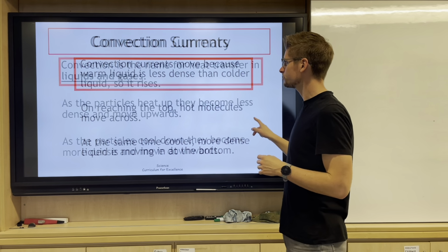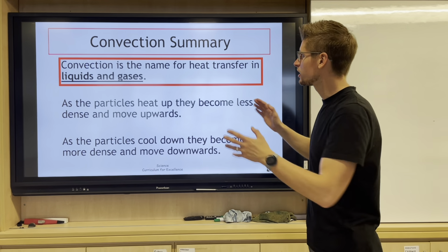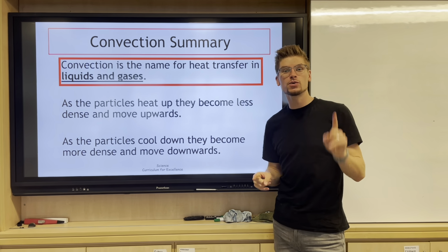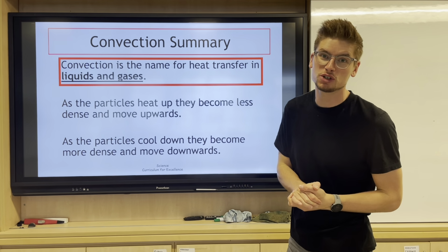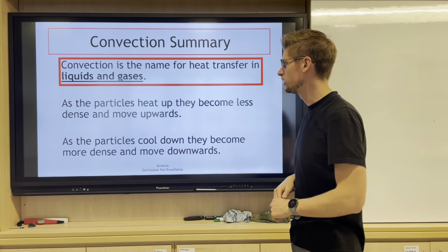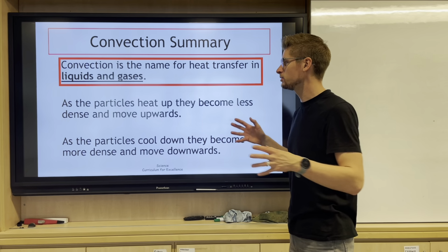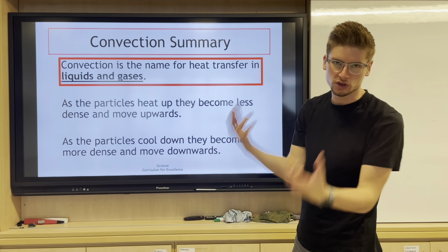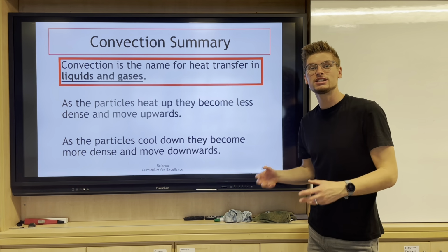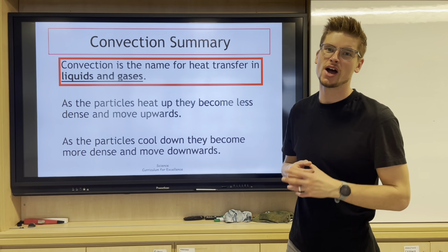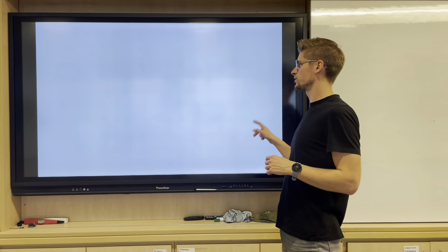All right? So, in summary, convection is the name for heat transfer in liquids and gases, much better than conduction. We'll leave the conduction to the solid. Okay? And as the particles heat up, they become less dense and move upwards, and then when they cool down, they go down. All right? So that's how we see convection works very well in liquids and gases.